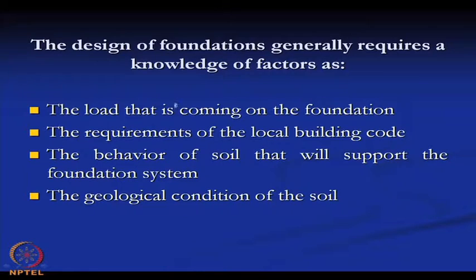We should know how much load is coming on the foundation. Then what are the required design codes, building codes of the area where we are designing the foundation, and the behavior of soil that will support the foundation system, what will be the soil properties. We should know the soil properties before we start the foundation design.